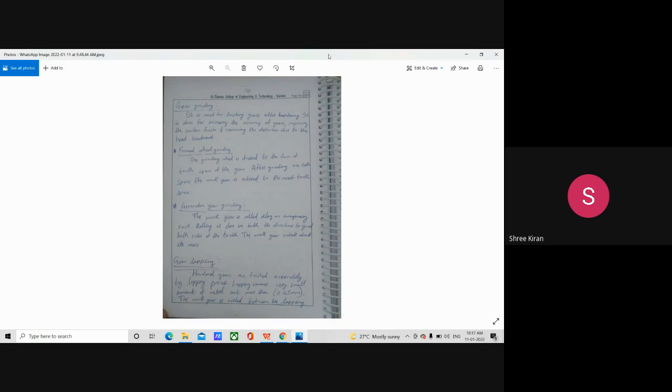We have already mentioned this in our gear burnishing process, where they are arranged at a 120 degree angle around the work gear. For material removal, the most suitable range is 120 degrees, in order to transmit power and remove material to an extent without much error, which happens at the time of gear lapping.